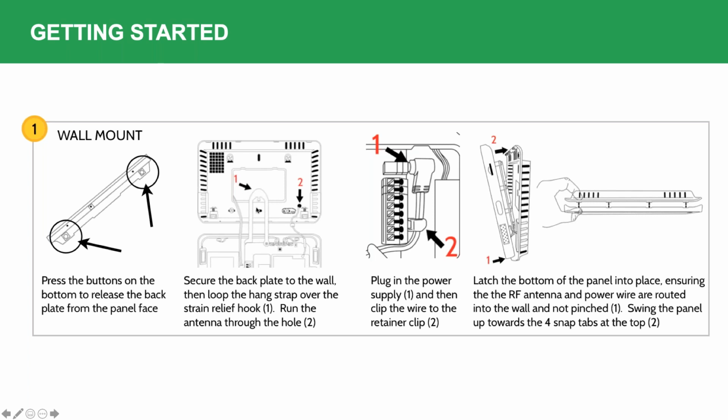We call this the technician's third hand. It allows you to hang the panel and still use both your hands when you're connecting things up. You're going to route that antenna out that little hole I mentioned earlier, the antenna routing hole. Once again, the reason this is important is for your range.